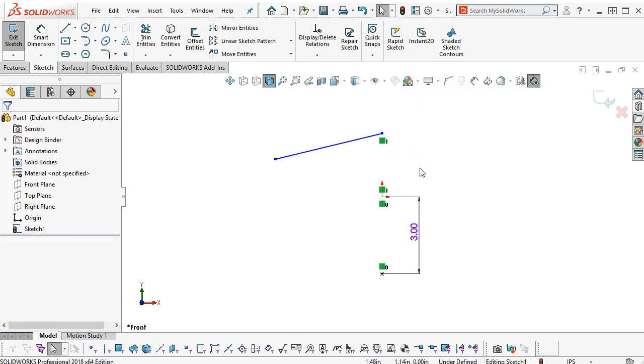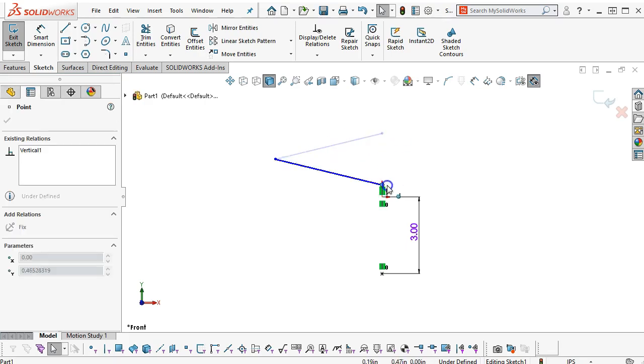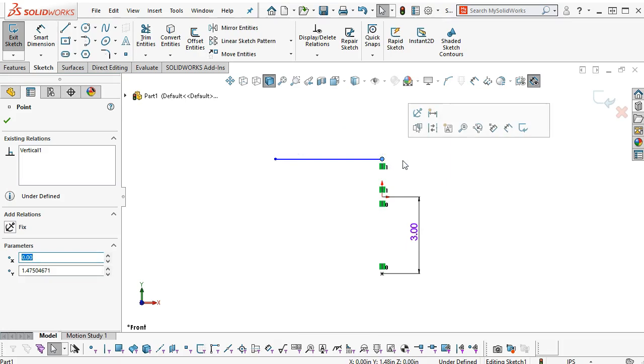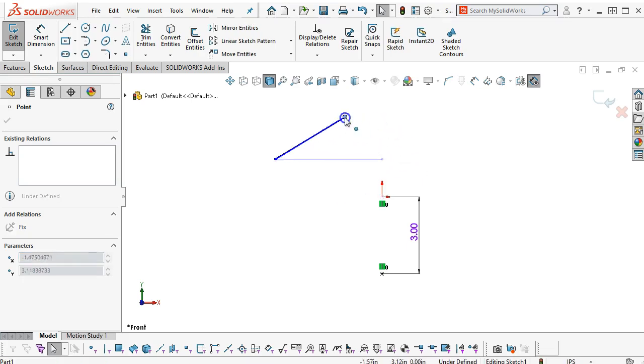All right, and I hesitate to use lock and fixed in any kind of terms because they have other connotations, but we are preventing it from moving in a fashion other than what we have determined we need it to move in. All right, so getting rid of a relation, if I highlight the box, it shows me the two objects that this was applied to. And if I hit delete on the keyboard, those relations go away, and now this is able to move again.